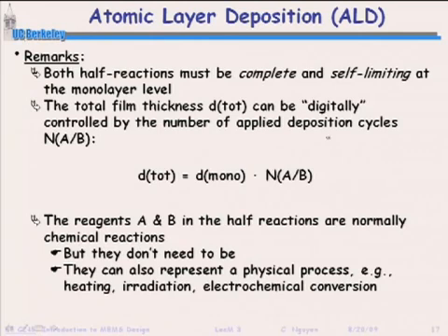Okay? Yes? Epitaxy, I think, was referred to before. You can do epitaxy of different things too, but usually silicon is the one. If you have a crystalline structure, you want to grow more of that crystalline structure, it's the same kind of thing. You're putting the gases in, you're taking it to a high temperature. You're actually growing, just like you're growing in a CVD process.